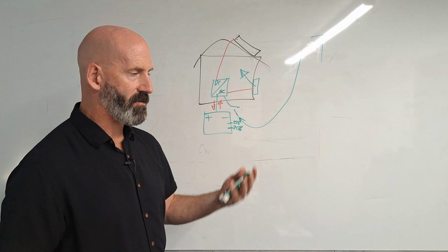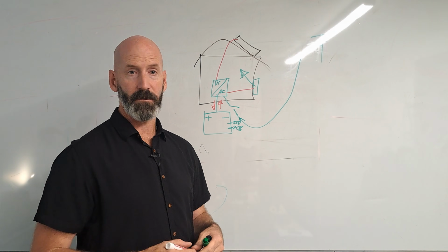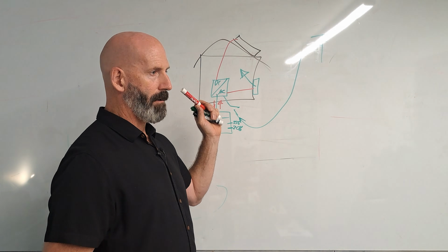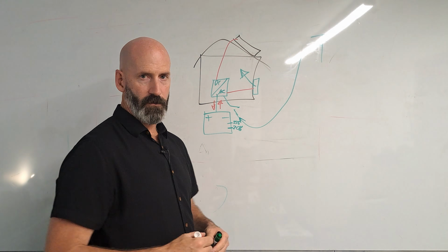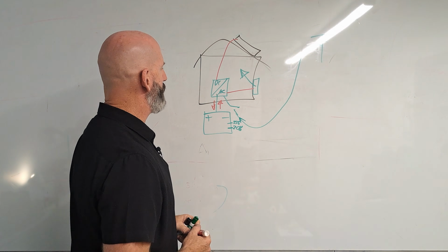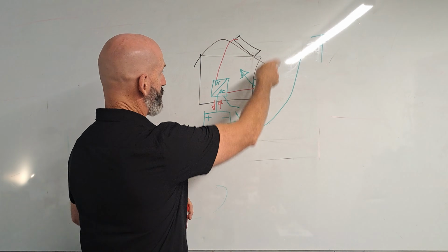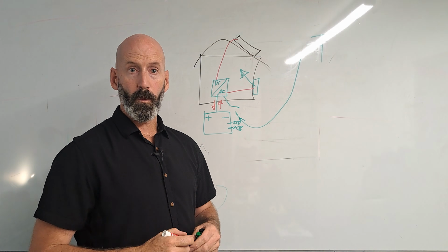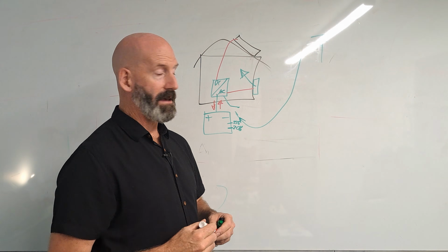Obviously with a grid connect, as soon as the grid goes out of balance, like if the voltage or the frequency drops out or you lose the grid, you just have no power. Hybrid, you'll have that backup from your battery, from your system. And with an off-grid, they're designed to have never been connected to the grid. What that means is if the grid drops out, it just breaks that. This system remains uninterrupted. You will have no idea that that system even stopped working. Your off-grid system will just have no backup power source at that point.